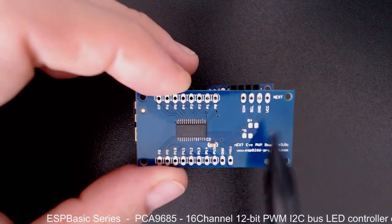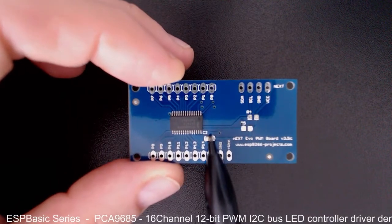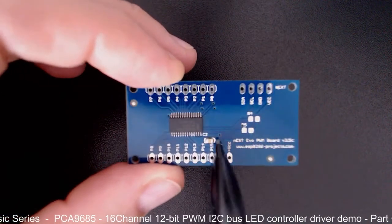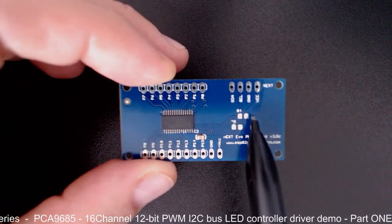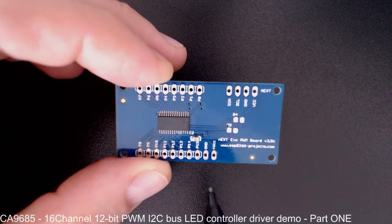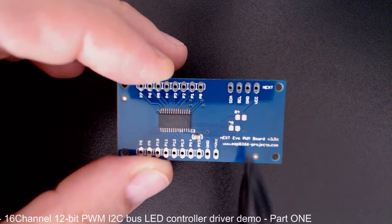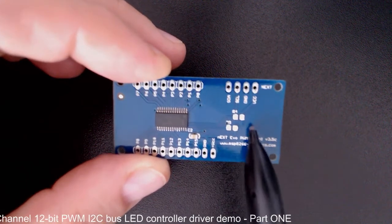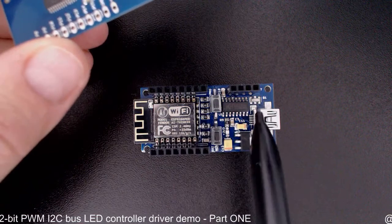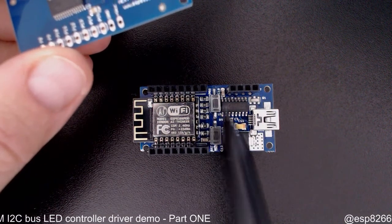You just have on it the PCA9685, and of course the proper decoupling cap. You have the option to install the required I2C pull-up resistors if you don't have them installed already. It's not the case with our Next Evolution board because we already have the resistors on the board.